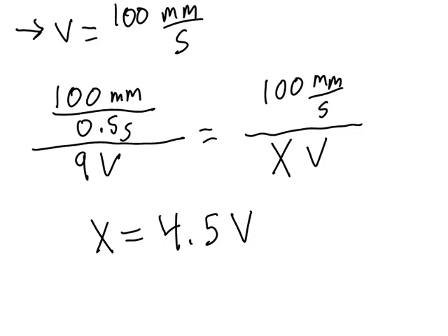Now remember from the last videos that I can't necessarily produce 4.5 volts. I'm going to assume that we're controlling this actuator with a digital pin of the microcontroller. So I'm going to be producing a pulse width modulated output. I need to calculate what the duty cycle is for this pulse width modulated signal.